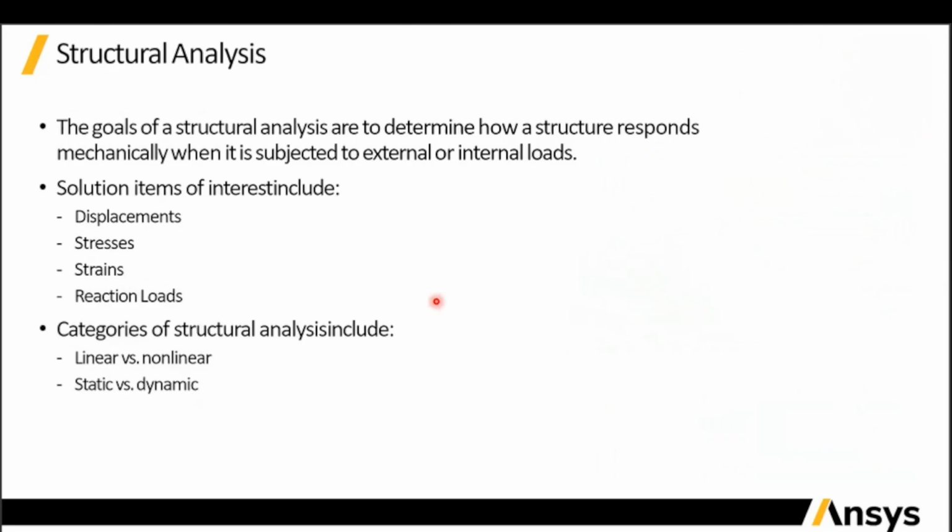The goals of structural analysis are to determine how a structure responds mechanically when it is subjected to external or internal loads. The solution items of interest include displacements, stresses, strains, and reaction loads. Then there are different categories of structural analysis: linear versus nonlinear analysis, and static versus dynamic analysis.